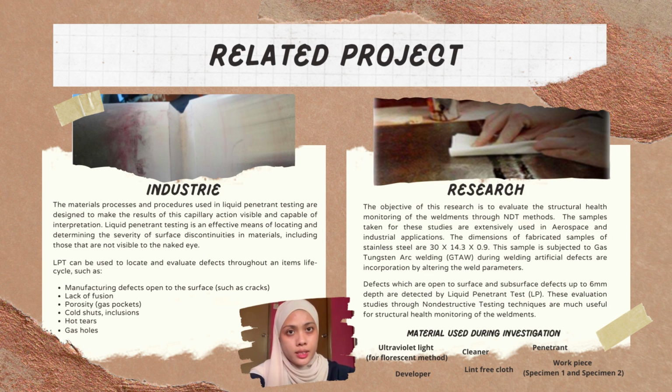In the research, the samples taken for these studies are extensively used in aerospace and industrial applications. The dimensions of the fabricated stainless steel samples are 30 mm by 40.3 mm by 0.9 mm. The samples are subjected to gas tungsten arc welding, GTAW. During welding, artificial defects are incorporated by altering the weld parameters.